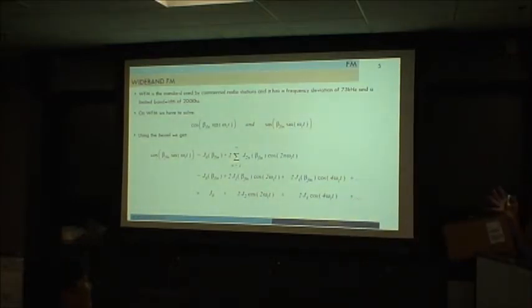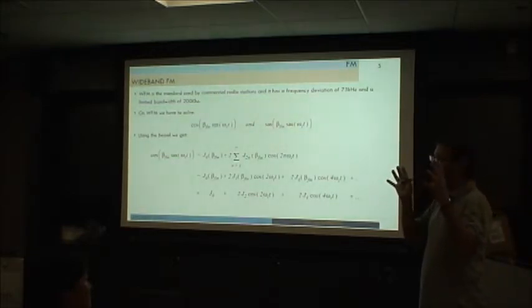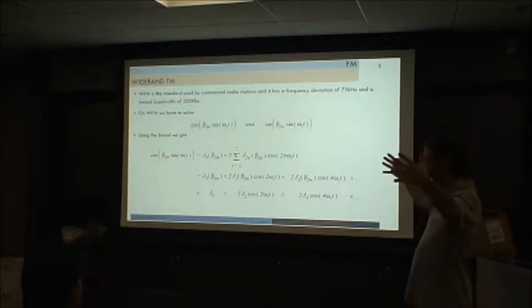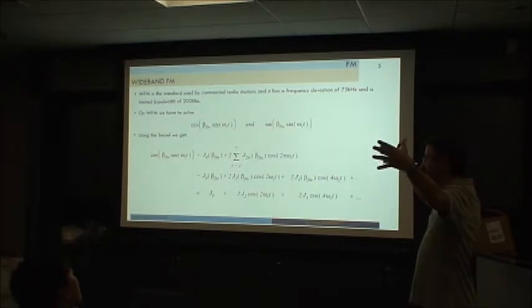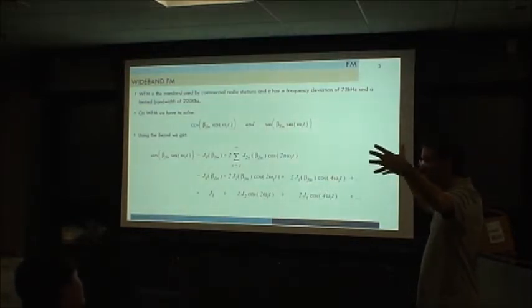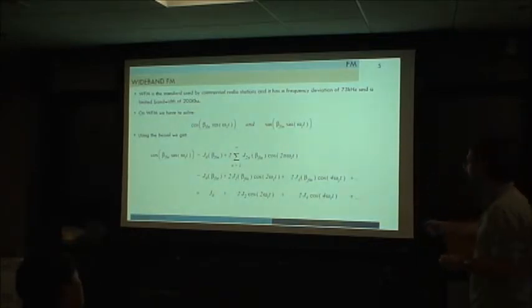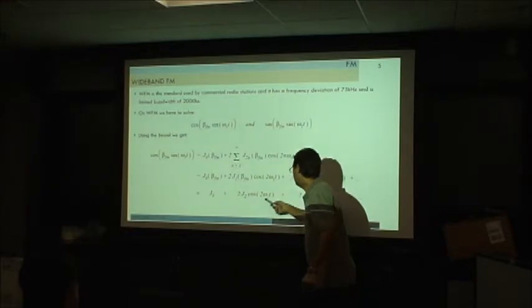So what I'm trying to tell you is that the spectrum of an FM is not as clear to see as the spectrum of an AM. That's why you just see a spectrum that is moving 200 kilohertz, but you cannot even see any particular tone there, because there are a lot of them. This could be really big.